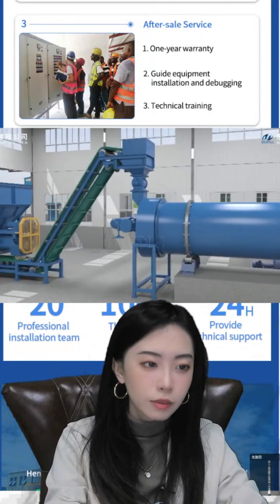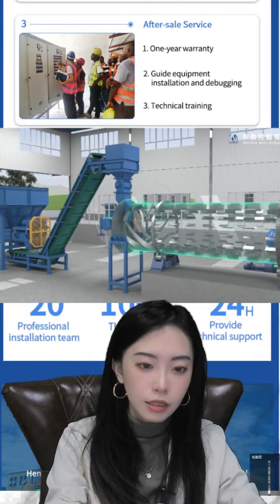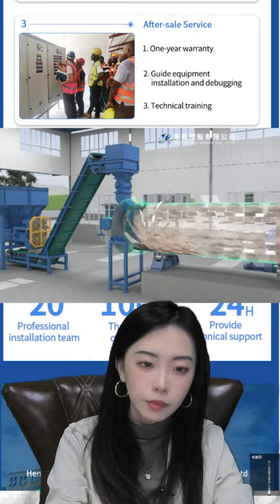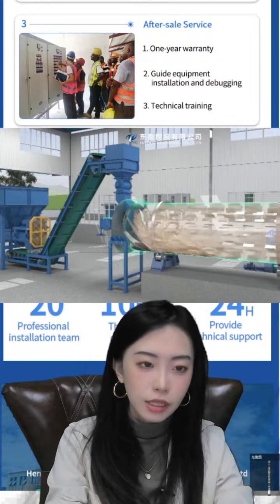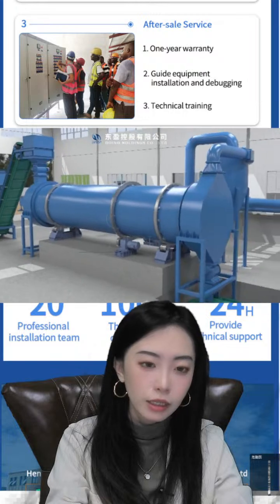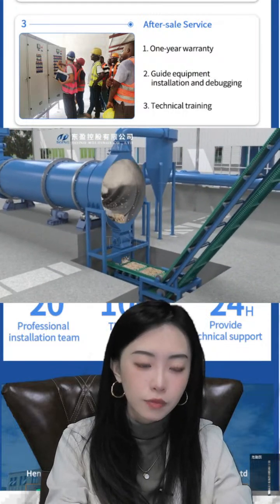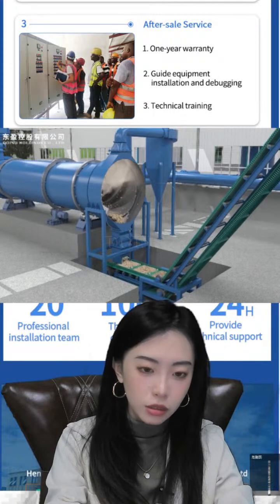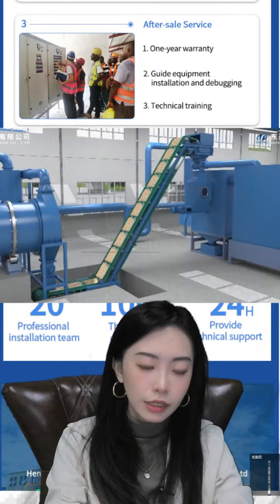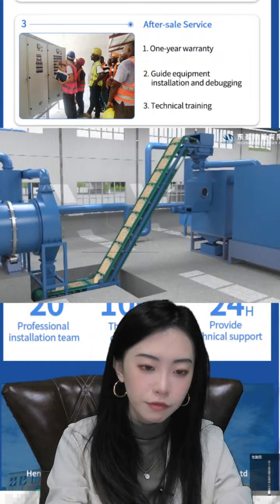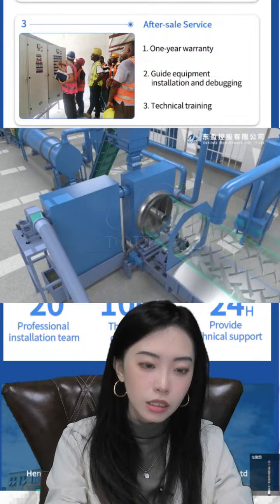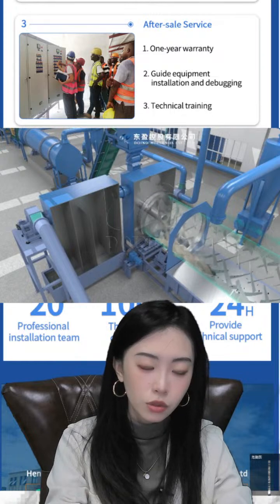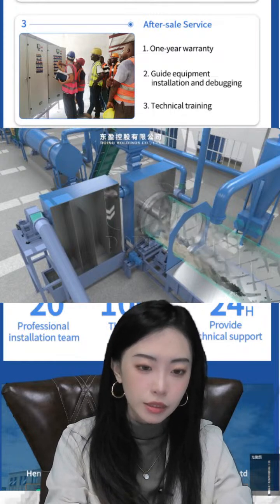And some other questions you may have, like you may be concerned about the temperature of the carbonization system. In the drying machine it is 200 to 300 degrees, and the carbonization system is 400 to 600. We have some standards for feeding the materials: the water content needs to be lower than 15 percent, and the material size needs to be controlled to lower than 20 millimeters.